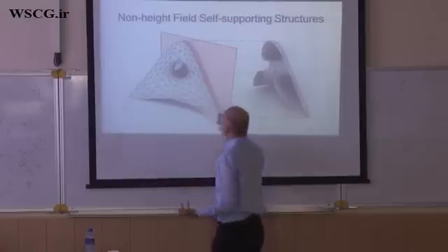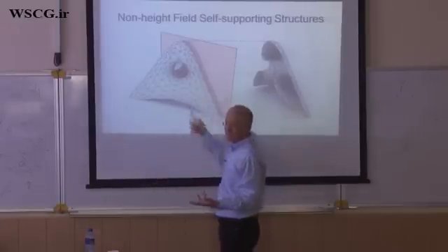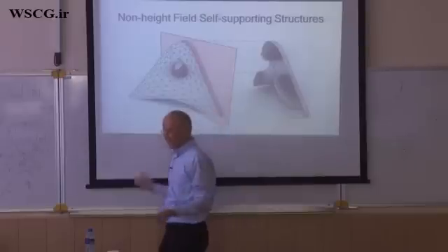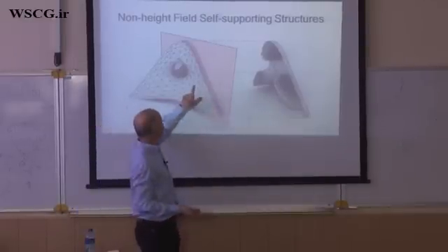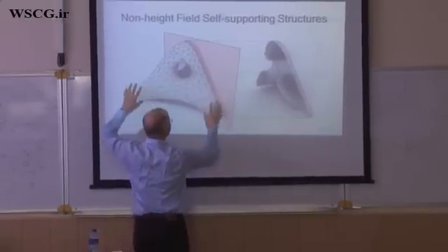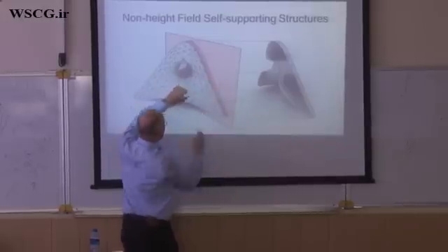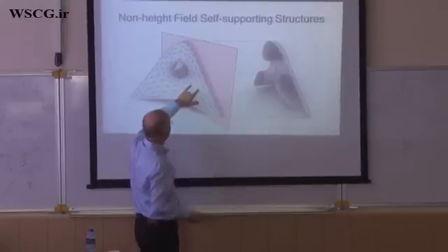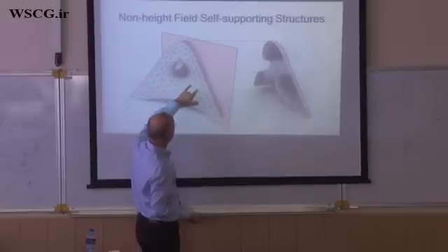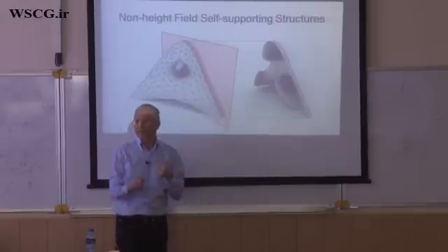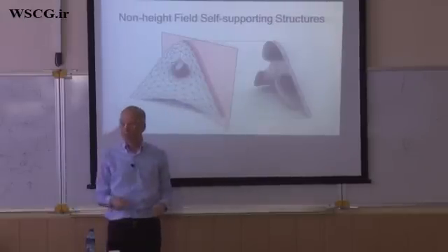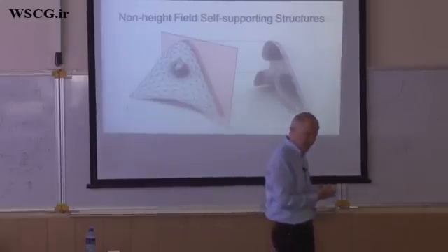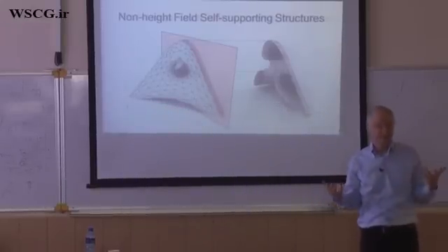But it is proportional, of course, to the area of such a face, the weight of a panel, and you have to distribute the entire mass into these vertices. Then the computation showed, with the same tool as I have shown in the video previously, this shape, and it is in force balance with compressive forces only, within the limits you would like to apply for this type of material, and therefore it is self-supporting.